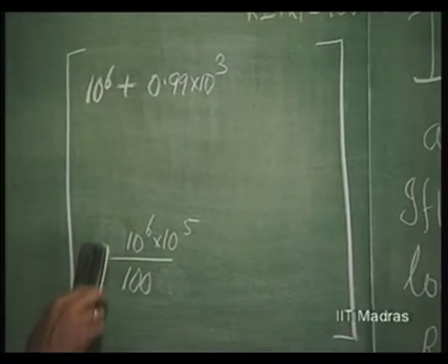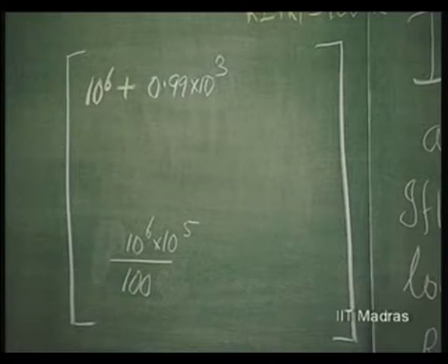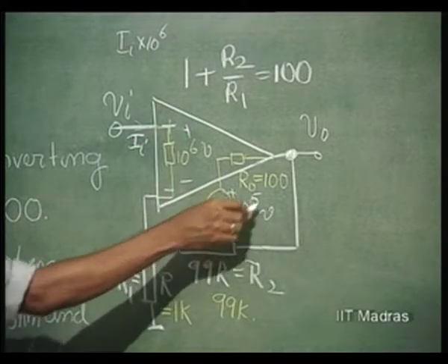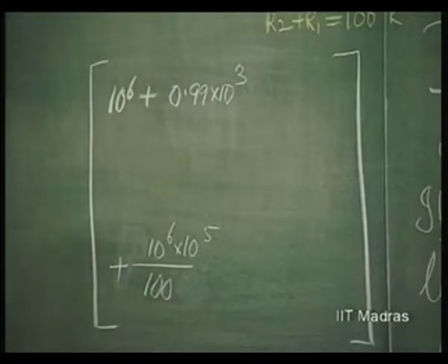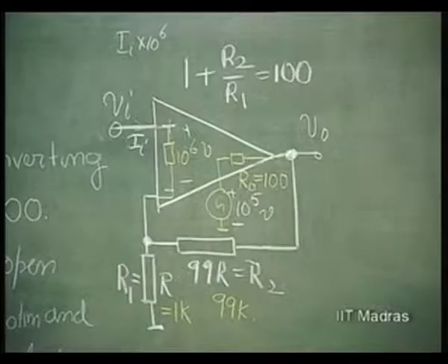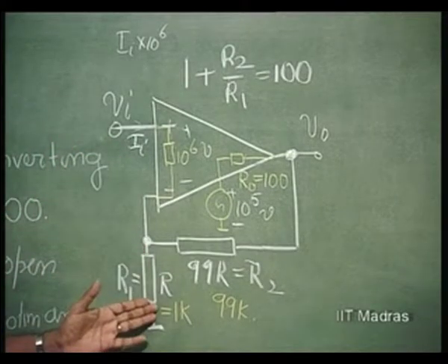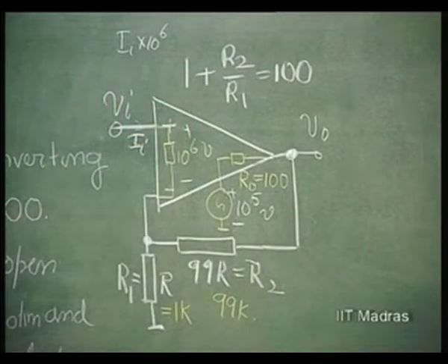So we'll get this as the output current gain, output to input current ratio. So the polarity of this, you can once again see here, this is plus minus, this is positive, and the current will be going in, so this is positive. The other current gain is due to II going there. 1K by 1K plus 99K will go in the opposite direction there.